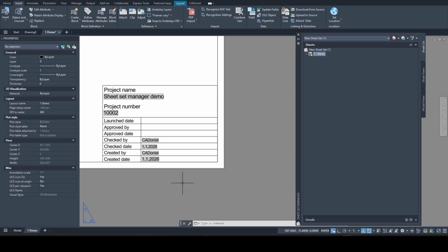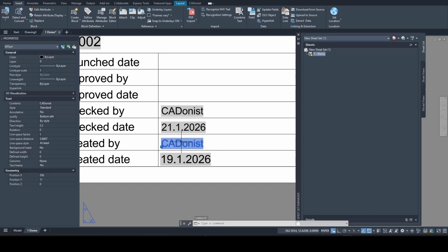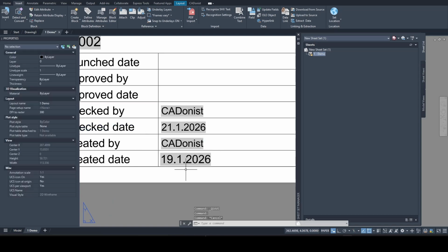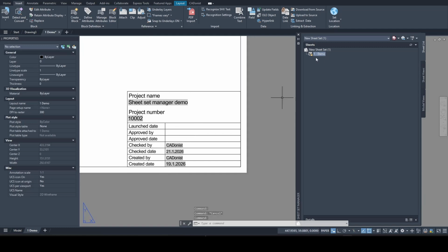Whenever you modify field values, you need to update the fields, either by using Update Fields or by saving the drawing. Once you save the document, the fields will be updated. As you may notice, when I inserted the fields earlier, I did not increase the font size to 2.5 mm for these 3 fields. In this case, we do not need to delete the sheet again. Instead, we can modify the template directly.